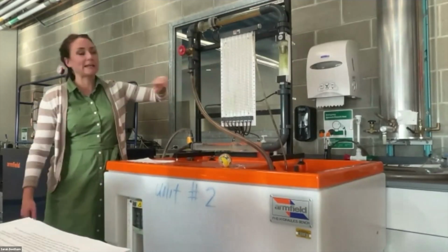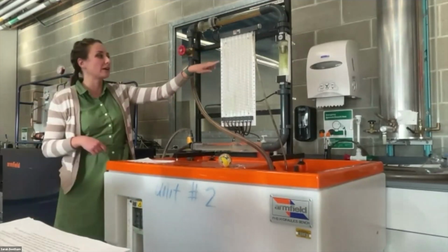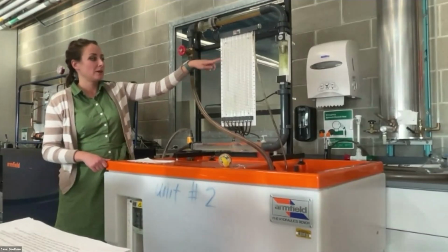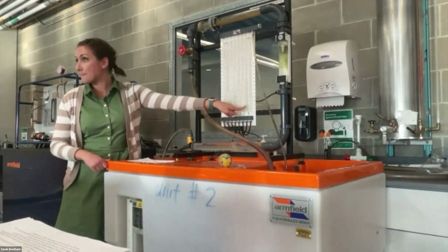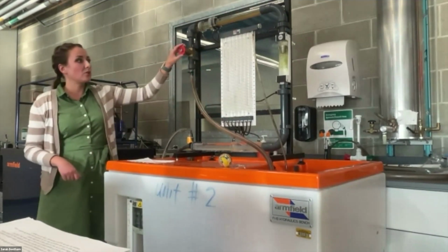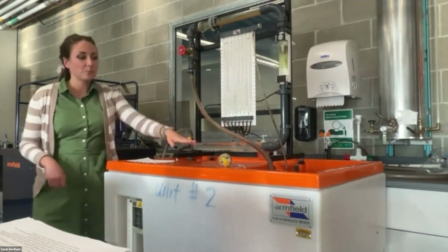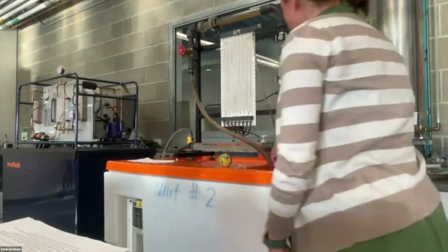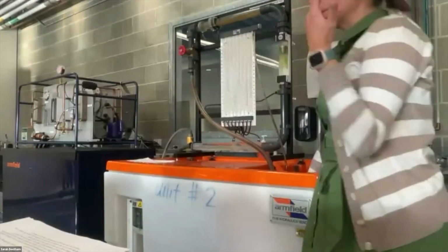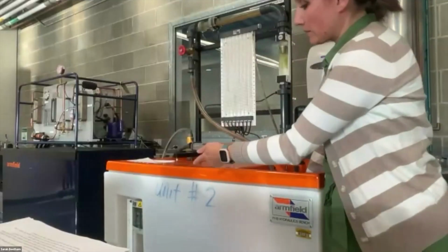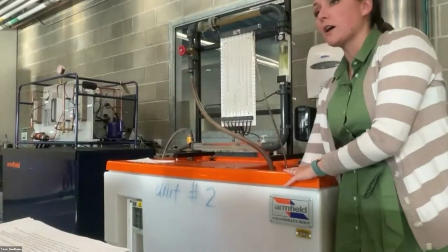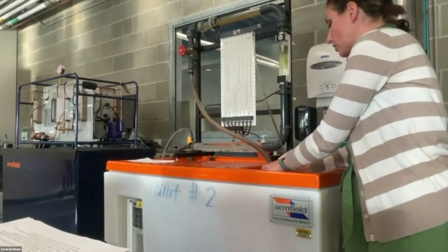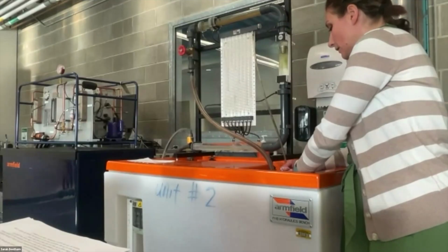So I probably can't see from back there, but if you want to come up and walk around, the highest value on my manometer is right here. And then the lowest one is down here. Okay. And so, once you get this set up, what you would do is measure what this says, measure all your barometer readings that you need to record. And then when your stopwatch person is ready and the person to measure the volume is ready, you'll plug the tank and then measure how much volume you collect over a set amount of time. Okay.